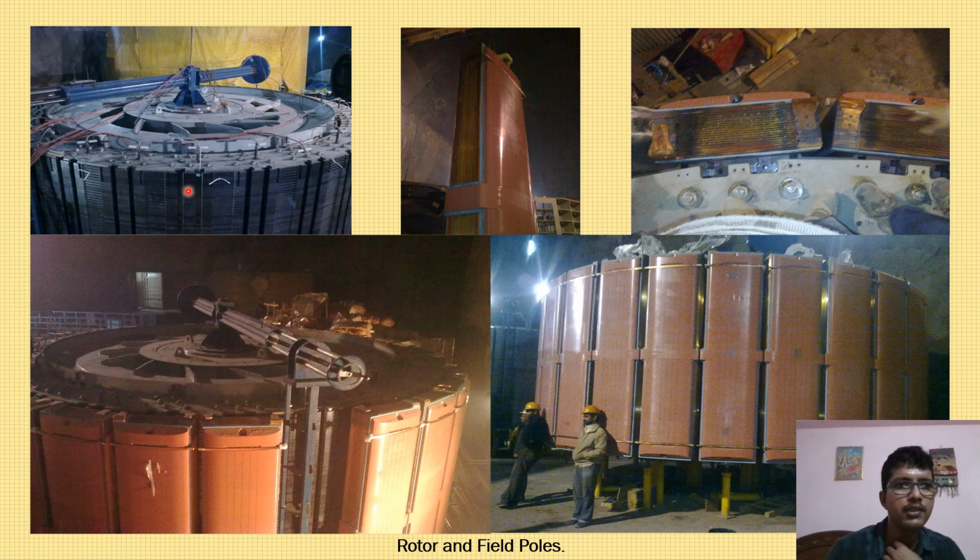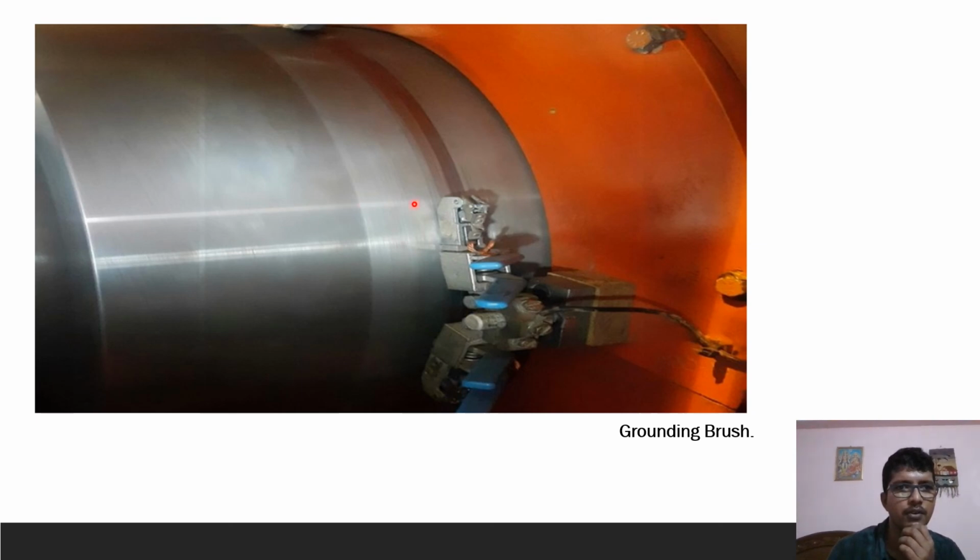Whenever there is a rotor earth fault, this is a structure without field poles installed. So whenever there is a rotor earth fault, the fault current will pass through this metallic structure to the shaft and go down, and finally will come out via the grounding brush. Right. There are two wires normally connected here. One is for grounding, another to the detector. So that current will go to the detector, as I've already shown in the first diagram, first slide. So it is a return current back to the network.